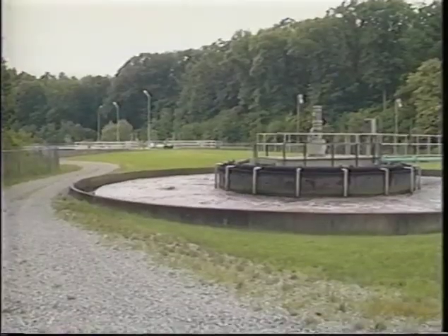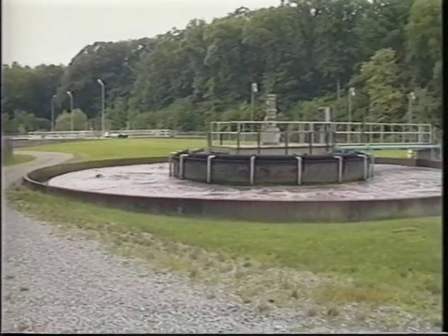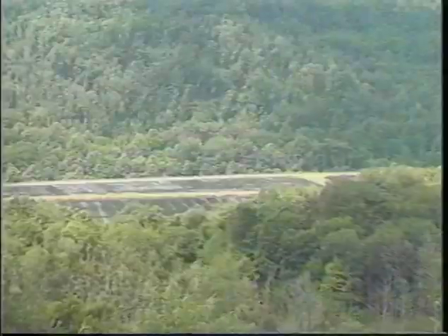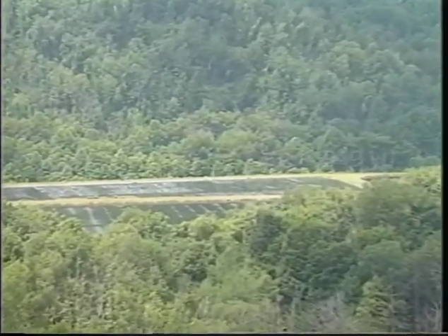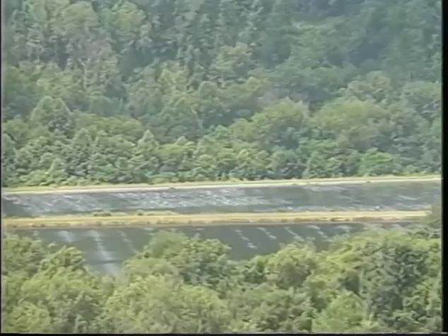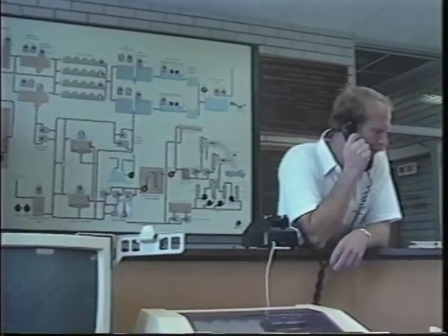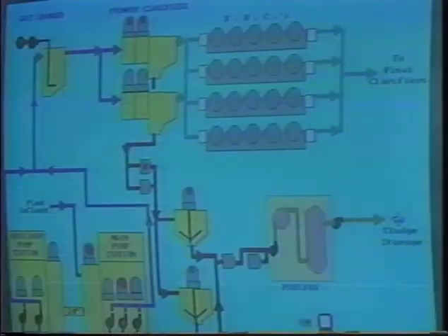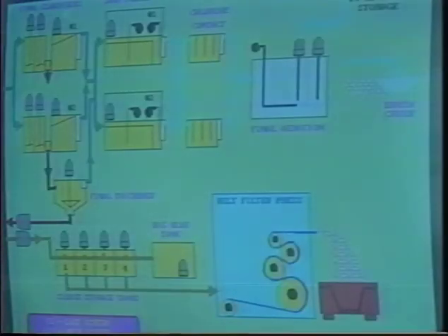Activated sludge systems are more compact and require a lot of operator attention, while lagoon systems require large amounts of land and are not quite as process control intensive. Both lagoon and activated sludge systems require skilled operators that are familiar with all aspects of the treatment system and a facility NPDES permit.